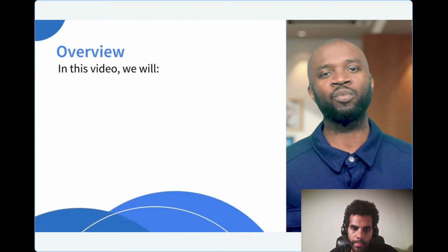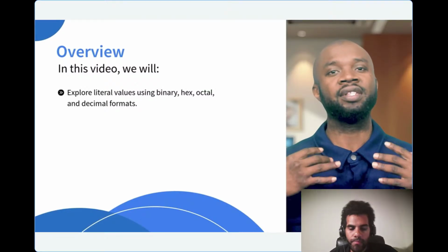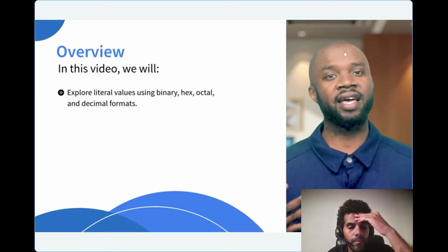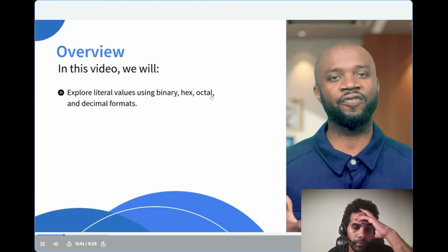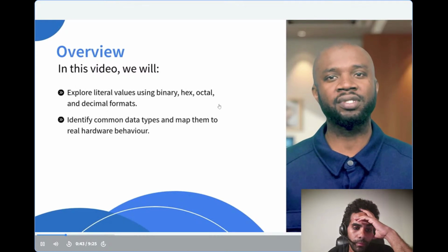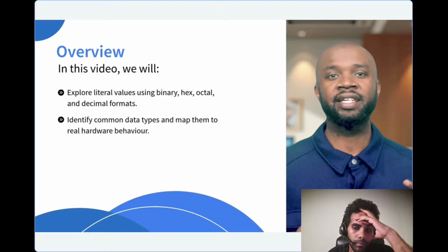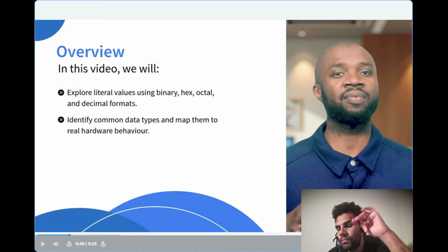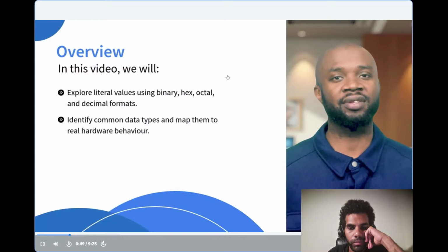So in this video, we're going to explore how literal values are represented in SystemVerilog using the binary, hex, octal, and decimal formats. We'll break down the most common SystemVerilog data types, including the binary numerical vector types and how they map to real hardware.